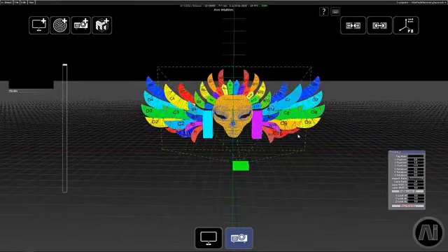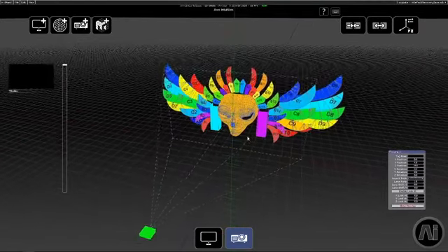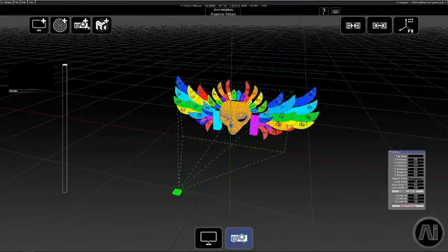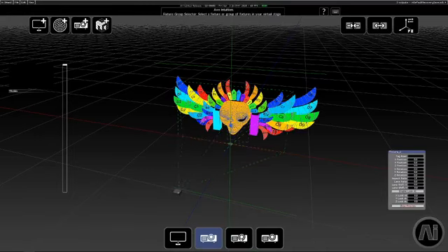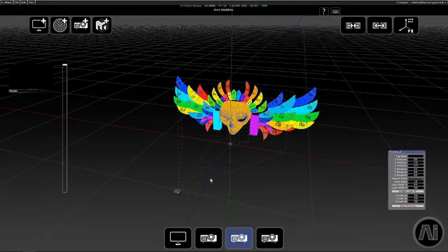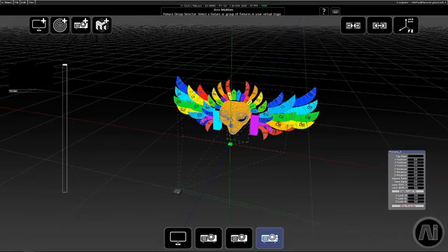Okay, so we've got our first projector in there. Let's get another 2 projectors in there. Quite a nice time saver with our projectors is that once I've got my other projectors in the project, I can copy: I select my first projector and press Ctrl C, select my second projector, Ctrl V, and that's going to paste all of those same parameters into that projector, and then the same on the third projector.